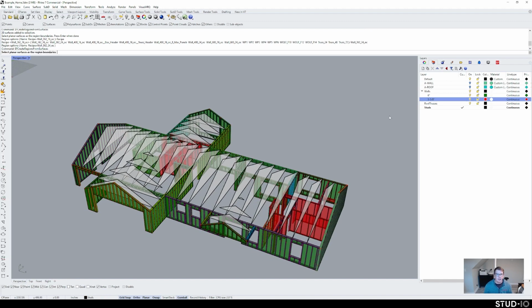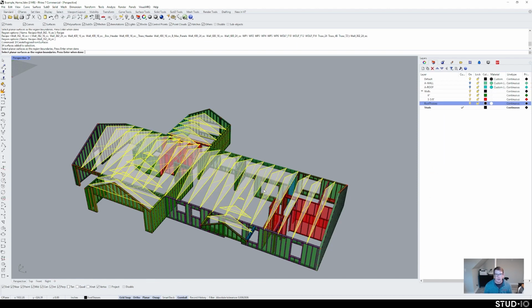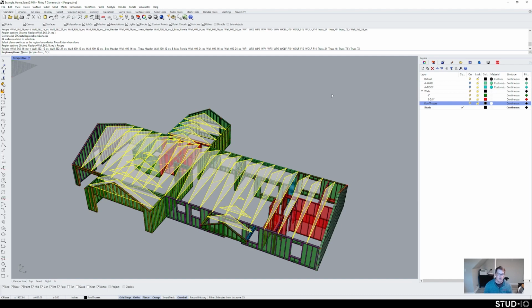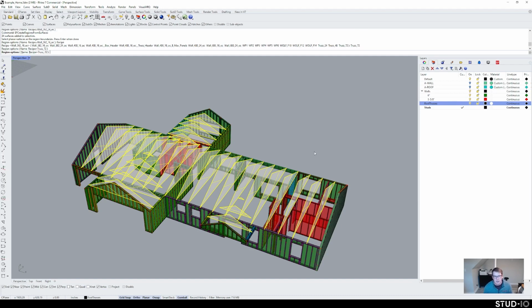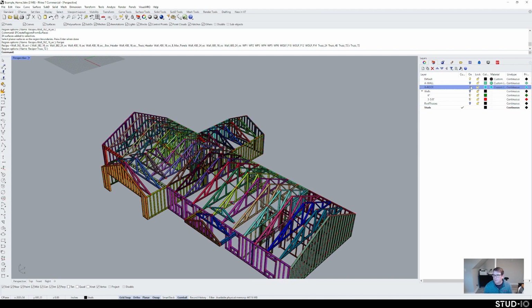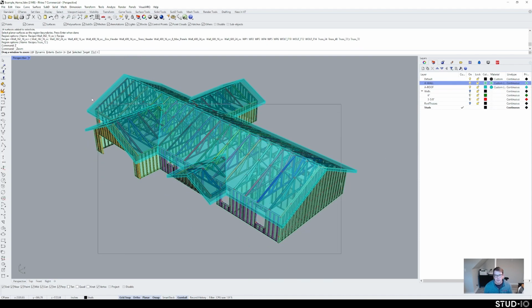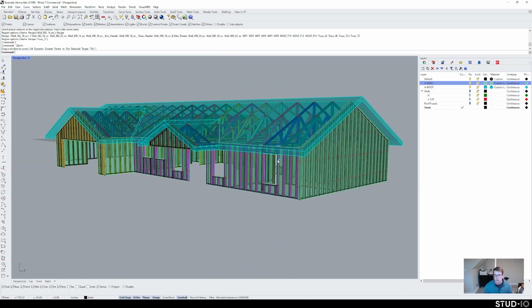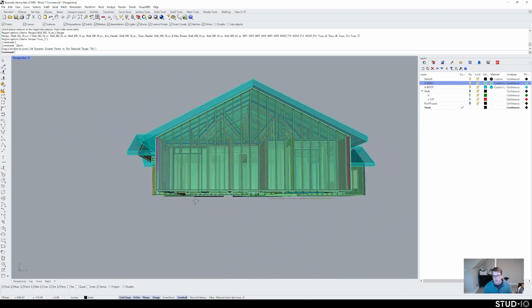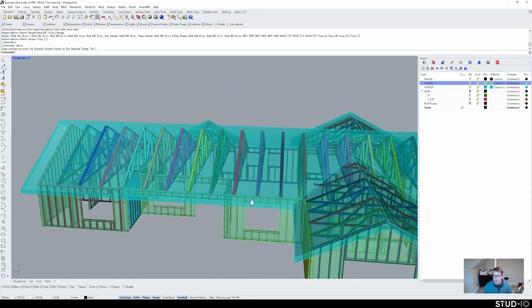And then same command, select all our roof trusses, change its recipe to trusses with 6 foot on center bays max, and you can see really quickly we've gone from just simple surfaces to fabrication ready regions for all of the framing that we need on this particular project.